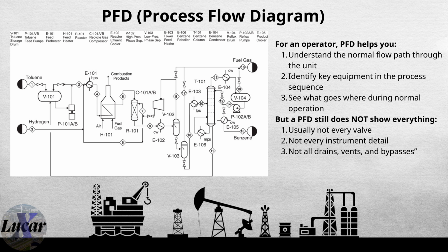To wrap up the PFD section, here are the key takeaways you should remember. For an operator, PFD helps you understand the normal flow path through the unit, identify key equipment in the process sequence, see what goes where during normal operation. But a PFD still does not show everything. Usually not every valve, not every instrument detail, not all drains, vents, and bypasses.